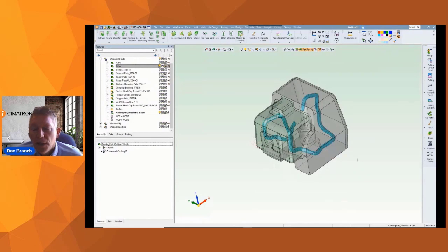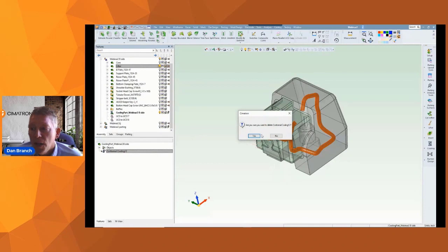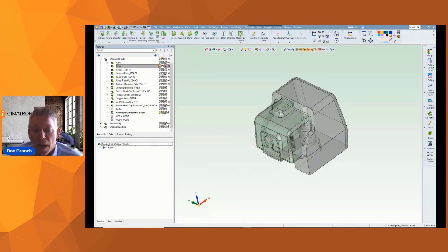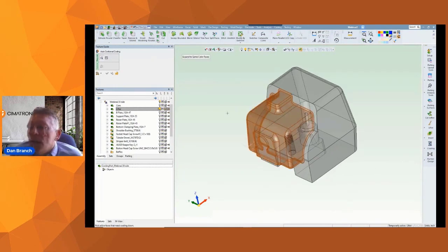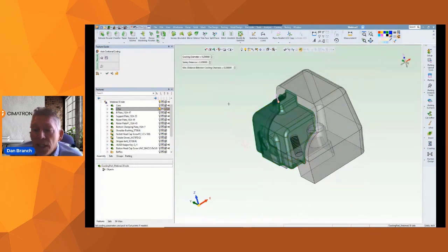Quite clearly, you can design a conformal water channel however you want to, but this is a task where automation can help. So we did take this idea one step farther. Rather than having to plot your own pathways, you can ask the system to automatically develop the best route through the part. The automatic conformal function wants to know what faces of the part are in need of cooling.